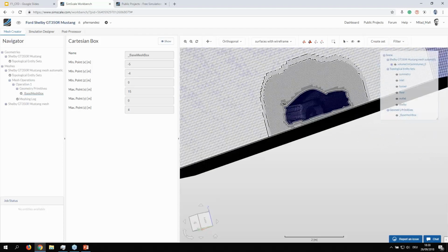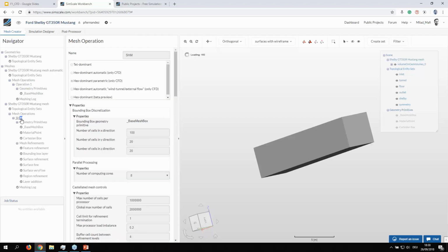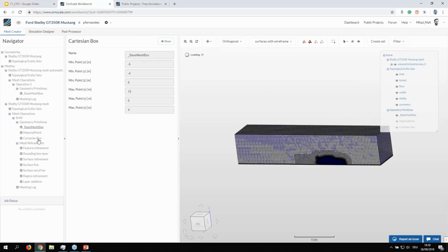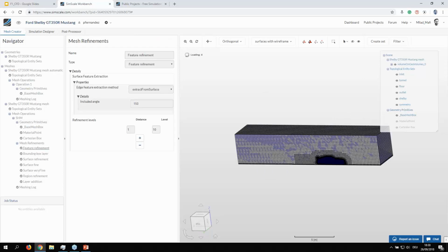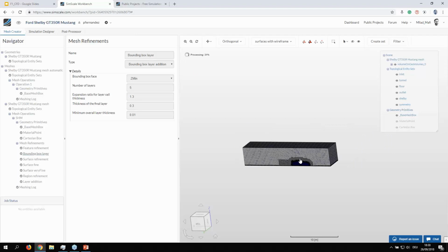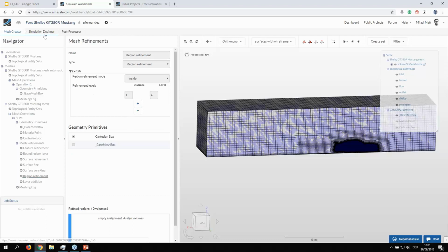But you can also create a mesh manually. In this case, we use snappyHexMesh, so we use hexahedral meshing, and you define the size of the wind tunnel box, and then you can define different features like refinement, for example, on the floor, which you can see here, to resolve the gradients. You can also define surface refinement and even region refinements.